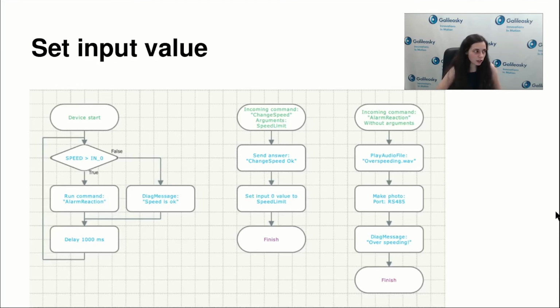Very good question. It takes into account a very important point: our device works only with integer values. If you need to do this kind of multiplication, you need to multiply 3.4 by 10, and after that divide at the side of the device or at the server side, because yes, we are not working with float data. Or you need to implement some kind of complicated mathematical actions yourself.